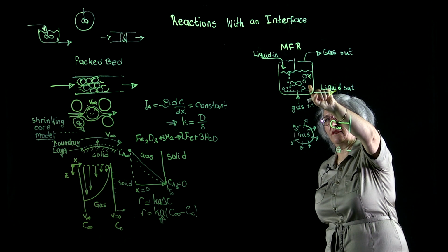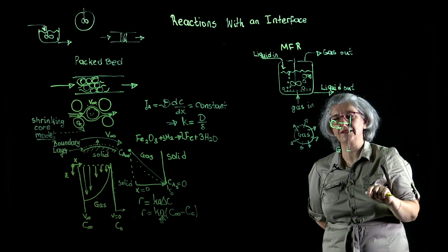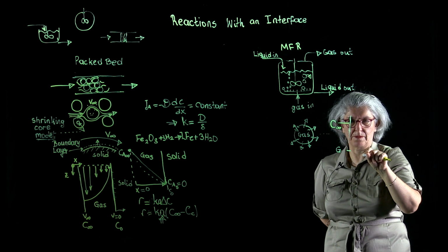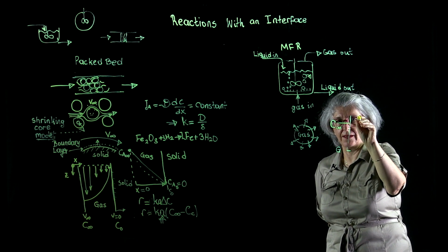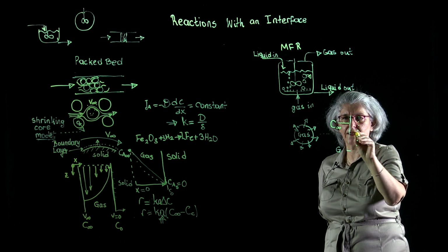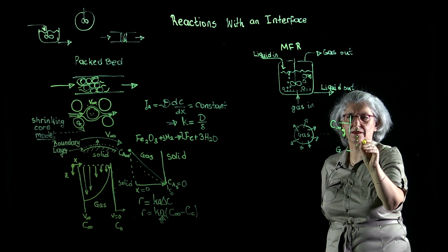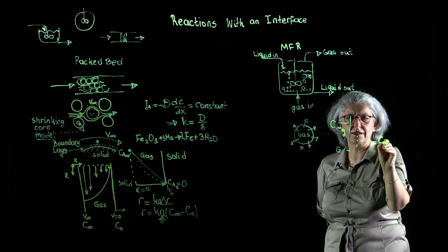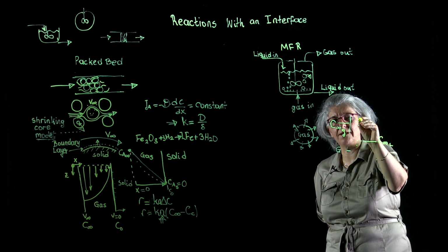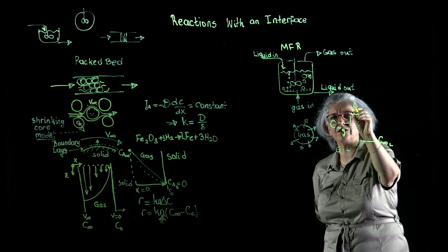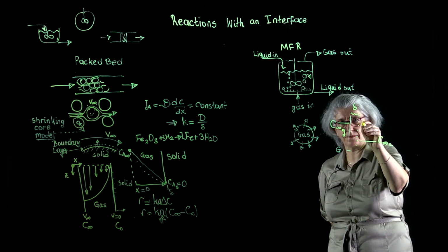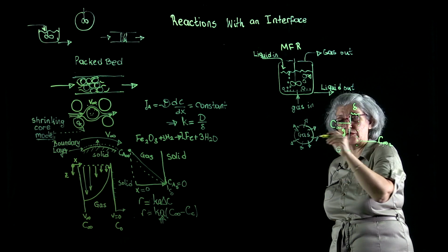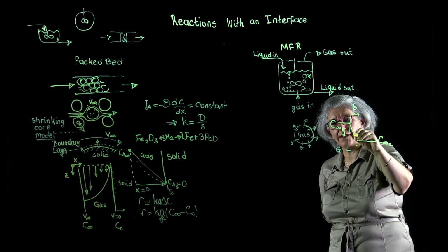But when we have a liquid which is being stirred by an impeller around this gas bubble, we will have some domain that is not going to behave like bulk, but beyond that we will have C infinity liquid. And here we have the boundary layer within the liquid domain. Again, from the two-film theory, constant molar flux gives us a flat concentration profile.